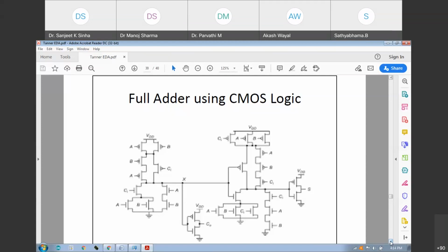For example, you can use a half adder. You can save it as a block and call that block 2 times in a full adder. And if you are going for a 4-bit full adder implementation, then you can design the full adder using 2 half adders, and you can design the 4-bit adder using 4 full adder modules. This is the way, hierarchy-wise. Otherwise it is not possible to accommodate all the transistors in a small window, right? But this full adder is possible to design in the same window, so we have designed those things. So next one, go for next.